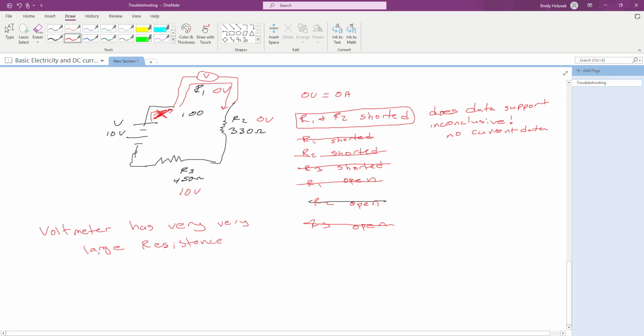The reason for that, and we will talk about this more when we get into parallel circuits, is that when we go to measure things, we are normally measuring in parallel. When we add this extra part to the circuit, we've added a separate current path that can flow that direction as well as through the resistor. We want this bleeder current, or meter current, however we want to look at it, to be as small as possible so I'm not affecting my whole circuit. So I have to have a very, very large resistance to create a very, very small current going through this meter.